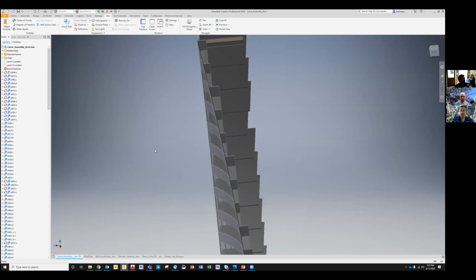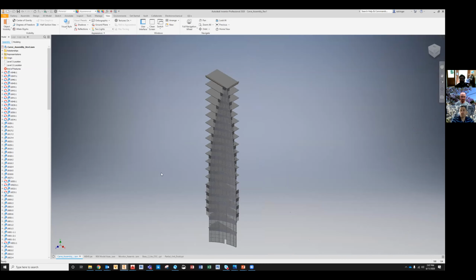Yeah, the steel beams aren't segmented to the same segment as the slab edge, and they hadn't accounted for the depth of the beams in some places and the sloping verticals. So they actually notched flanges out in places to accommodate that. But this was the starting point for us, and it was a lot of trial and error on Ed and I's part. We were both learning Inventor and figuring out how to do this really complex geometry in it and get it so that we could fabricate.